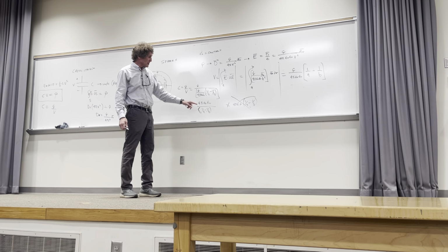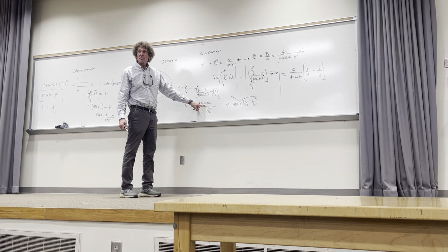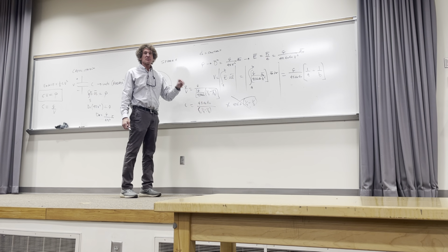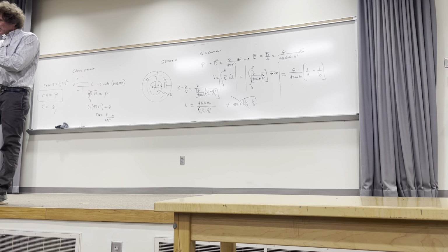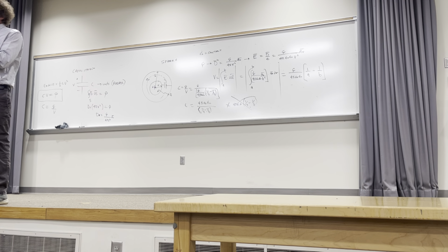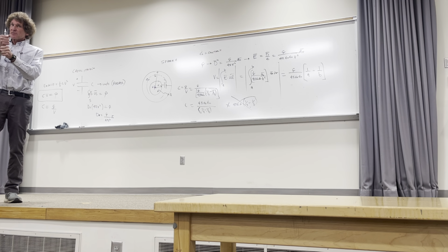Now, what they're really talking about is something with enormously large epsilon relative. That's a material science kind of problem. They have to have a dielectric that can stretch a long way without hitting some limits of stretching. So there can't be an arc over or anything like that. And then release that energy back into the system. Remember I told you these little dipoles stretch and store energy?